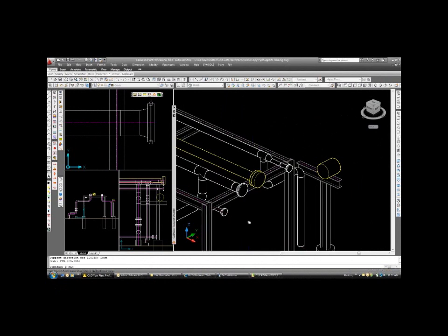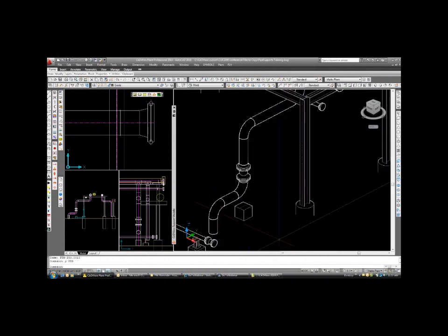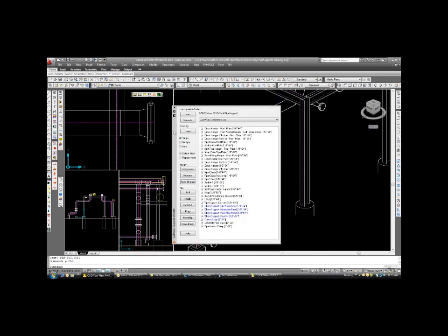So I'm going to scan over here to this pipe, and I'm going to pick another pipe support function called the base L. And it's the pipe stanchion right here. And here's the pipe stanchion with a plate on the bottom. You notice that they're in a different color. That's because you select elbows and pipe as different support entities that you want to select. And you also select those entities differently when you go to customize a file. So we'll pick the elbow support.